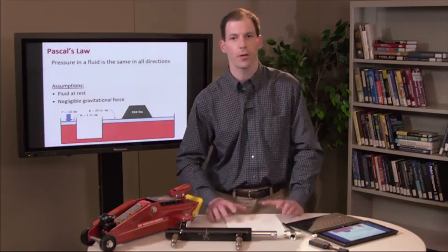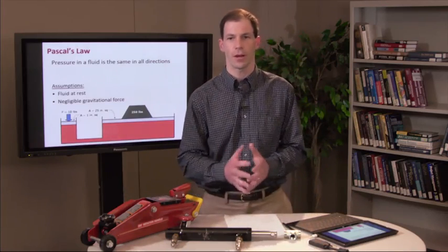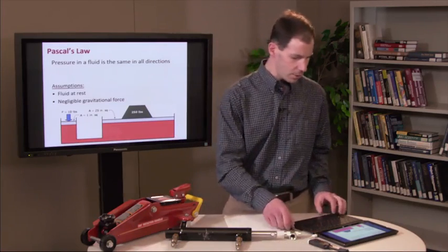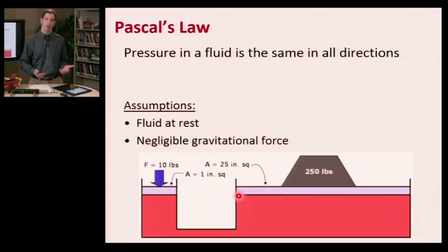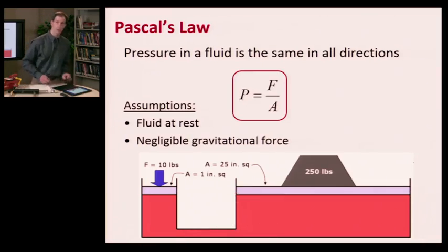But what Pascal's law allows us to do is, if you look at this system I've got on the slide, where I've got two different areas here, and on the left side I've got this small area piston connected to a larger area piston over here. Well, Pascal's law is telling us that the pressure in that fluid is the same in all locations. And because the pressure is the same, and I know that the pressure is the force divided by the area, I have different areas, so I can create force amplification.